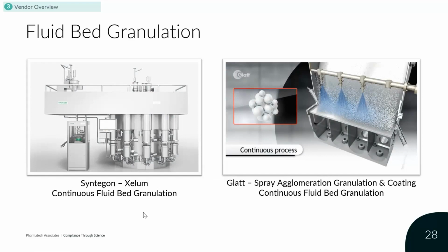You feed in material continuously into a blending device, you go into this fluid bed granulation system where the granulation takes place and at the same time drying happens, but you have these five cells where this is happening. So you have this semi-continuous element again, and then you use the material plugs of the granulated material conveying it to the compression machine.